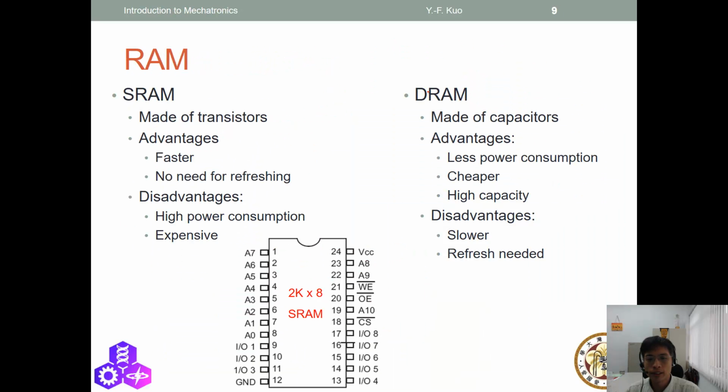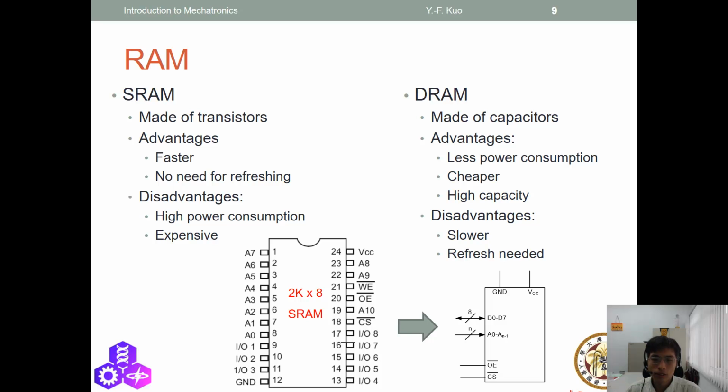number 9. So this is a memory device. Remember, for a memory device we have data pins. So we have 8 data pins. You can see these are the 8 data pins. Although we only draw one line, when we draw the line in this way, that means there are 8 lines. And we also have several address pins. In this example we have 8 address pins.